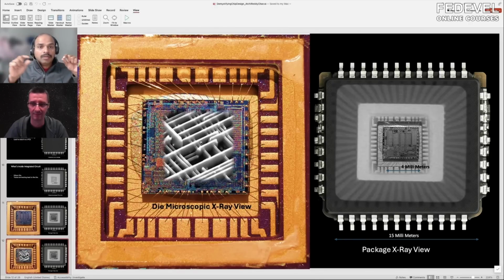Just like birds migrate or people migrate, electrons do migrate. Wherever it is migrating from becomes an empty space. It's called an open. Now there is no path, so you don't see the signal passing through. And where it is accumulating, there are neighboring tracks, and usually their spacings are very thin. What happens if it bulges? It short circuits. So these things can happen.